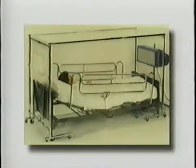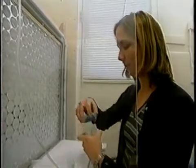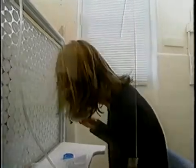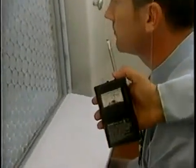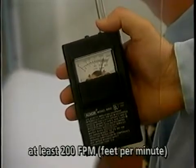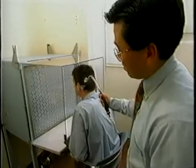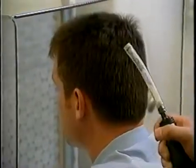The safest option is to use a source control device, such as a sputum induction booth or tent, which completely encloses the patient, or a partial sputum induction hood, such as this. The advantage of these devices is that they capture infectious particles so that they are not released into general room air. You should also check using a velometer that the air velocity is at least 200 feet per minute at the side of the patient's head. The hood should be placed away from other air currents, such as those created by open doors or windows. This can be verified by smoke testing.